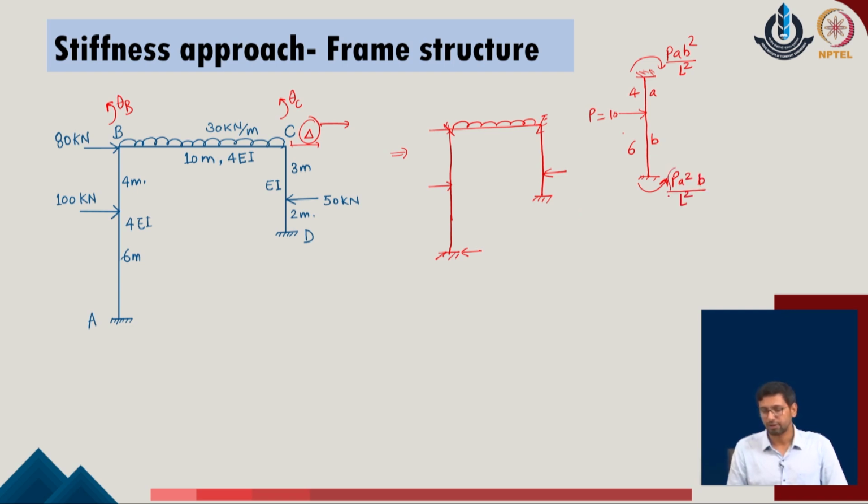As we have calculated the values of these end moments of the given system, we can also calculate that these values will not be giving us the same amount of moment, which typically happens with the point of the loading if it is centrally placed. So, now with respect to this net moment imbalance, we need to also generate the support reactions which will be available at the two ends of the given system, and these support reactions will be added over and above the actual reaction which is provided by this given system as a simple pin jointed part of the given problem.